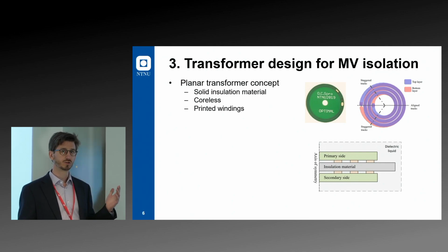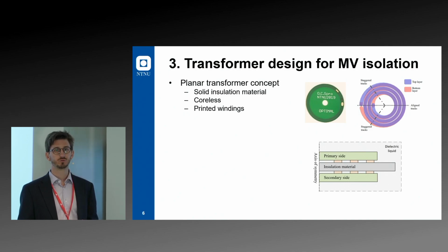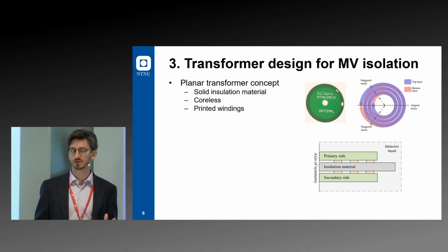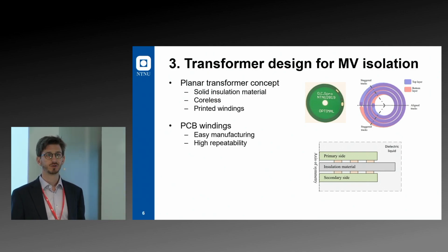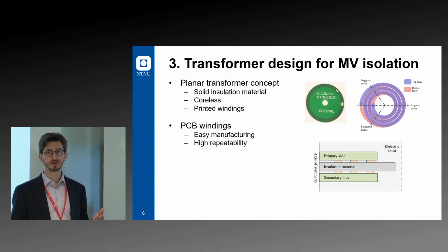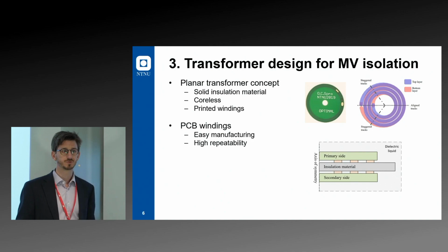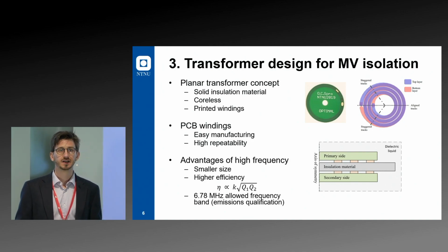So we're also choosing a coreless concept to really focus on that voltage isolation part. Now, using printed windings, we have very easy manufacturing and high repeatability. That's good for making products. But there's one disadvantage, which I'll come to in the next slide.